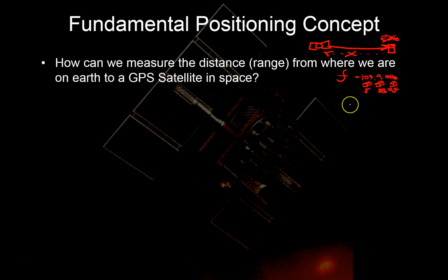Now in GPS, it's very similar. We have a satellite that acts like the radio station. It's broadcasting on a specific frequency. So for us, 1575.42 megahertz is L1. And again, there are packets coming down. In this case, the packets are used in a couple of senses. One is the codes, the CA code. So this is a CA code packet.